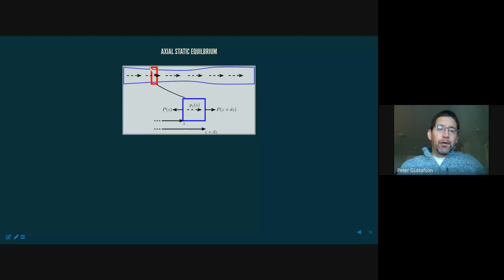We can take a free body diagram by taking a cut on each side. We're going to include the entire beam height and width in our cut, but we're only including a small portion of the axial length of the beam. And we know that we can have a resultant on the negative face, and the corresponding arrow is pointing in the negative direction. We're talking now in the stress sense. It is a tensile force, which is positive on a positive face or negative on a negative face. And note that again the z-axis is the long axis of the beam. So the little differential cut we took was of width dz along that axis. So we've got a normal resultant P on the left side at position Z. We've got a normal resultant to the right, P, at the position Z plus dz.